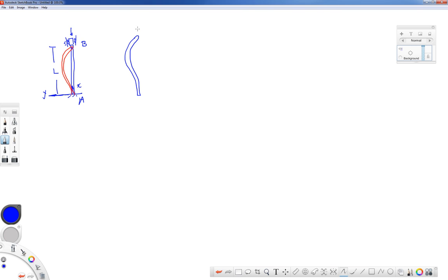But we have our fixed end down here at A, which we can have a horizontal force. Call that the y direction, so that's AY. We can have an axial force, AX, and the fixed end can support a moment. I'll call that MA. Up at the top, we have a vertical force P and a horizontal force that goes this way, I'll call it HB for the horizontal force at B. We don't have a moment up at the top because it's a pin condition up at the top.